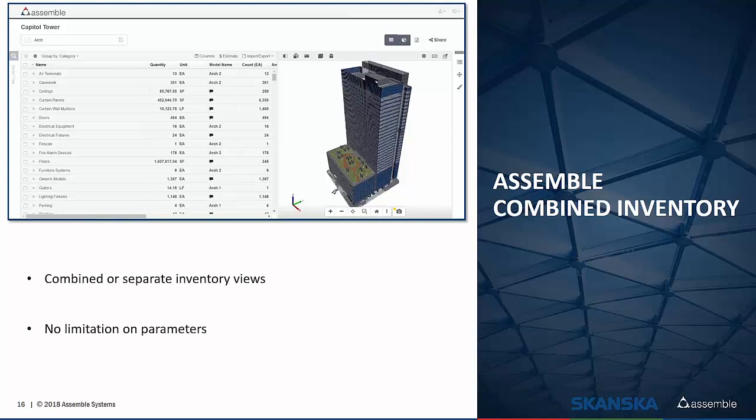We federate models together, so if your designers are working in 8 different models, you can put all of those into the same data table and same view. Then you can query across all of that data consistently, however you key in your cost code information, your bid package information, or your work packages, whatever it may be. You have that consistent set of parameters across all models, irrelevant of the model version or revision of that file. We're an object-based database, so all of this information can live on even though the model is being updated, version to version.